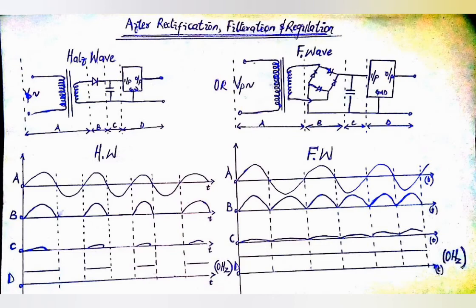The second additional stage is regulation. Every designer has a desired output rating. This value is meant to be steady. For a charger circuit aimed to produce 12 volts DC, at every point in time, within the rated range of input voltage, 12 volts must be present at the output of the rectifier circuit. There is no ideal circuit, and because of this, there are often fluctuations in the output of filtered and/or rectifier circuits. For this reason, regulation is employed to maintain a steady output voltage value.